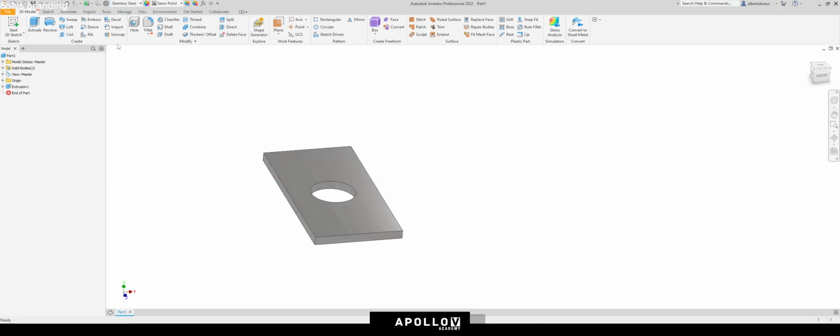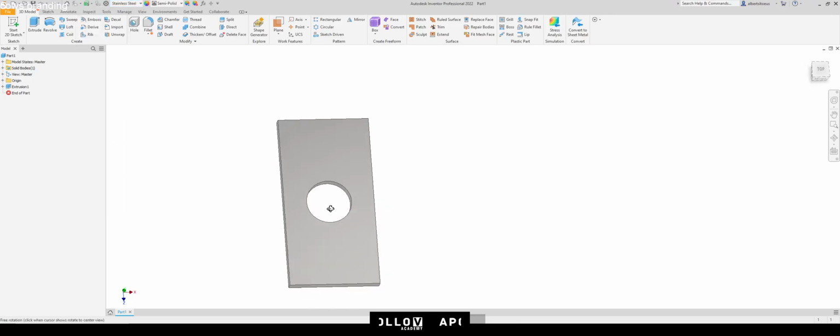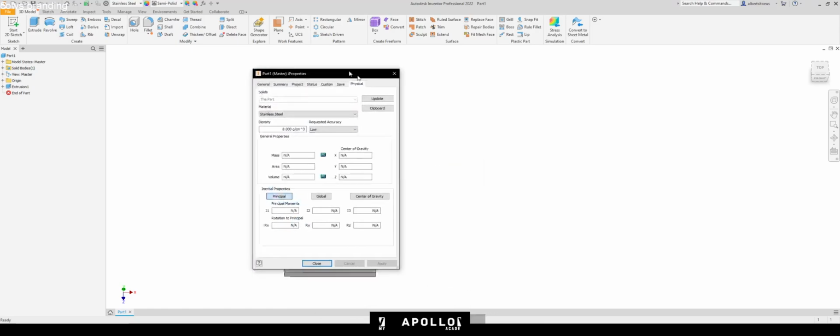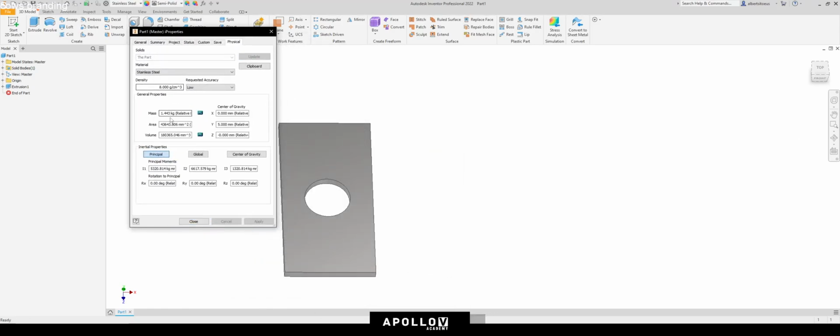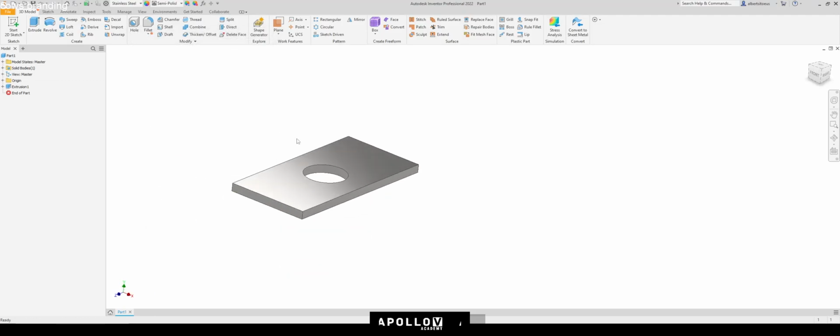And the cool thing about using materials inside of Inventor is they allow you to specify the material. And once you specify the material, you can get stuff like physical properties, such as what is the weight of the file. So that if you're trying to import these things as parts from China, let's say, then at least you know that all 100,000 of these parts are going to weigh exactly X amount. Well, maybe not exactly because of packaging and stuff like that, but at least you got a decent, more or less value before you go and commit thousands, if not millions of rands to something.